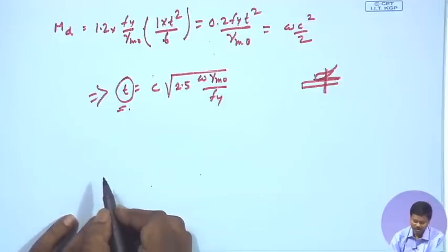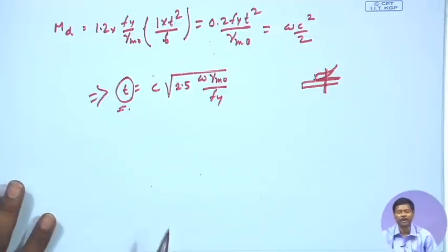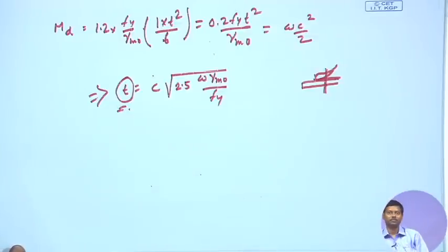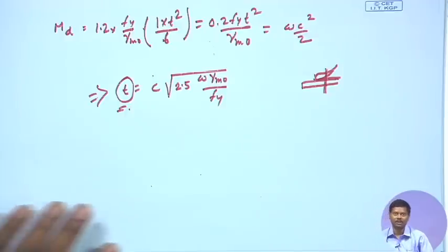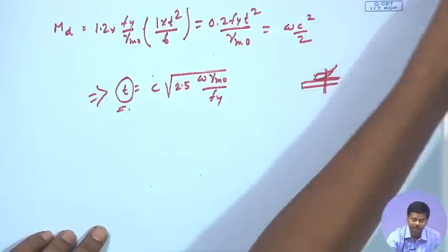However, this is true if we are going to provide Gusset angle, and Gusset angle we provide generally when it is bolted connections, but for welded connections we do not need to provide Gusset angle. Therefore, the thickness of the base plate will be the requirement of the base plate, that means whatever T we are going to get, that will be the thickness of the base plate. We do not have to do anything extra, right.